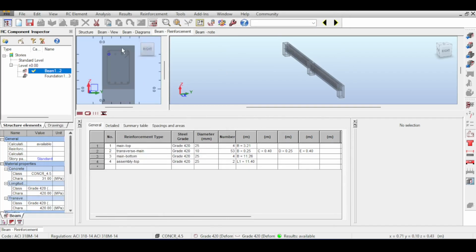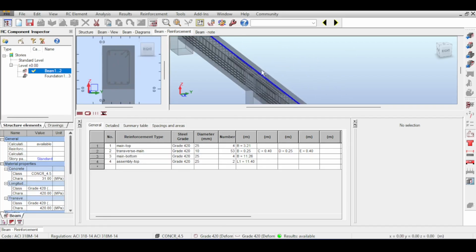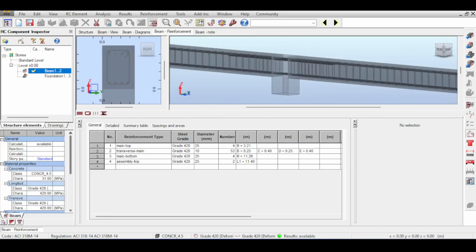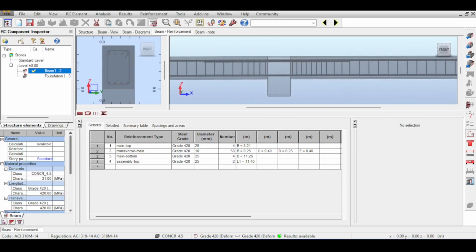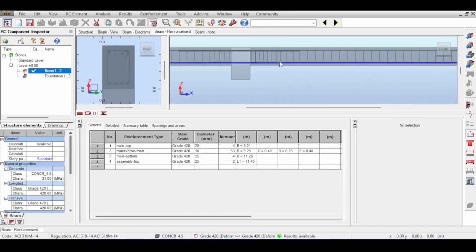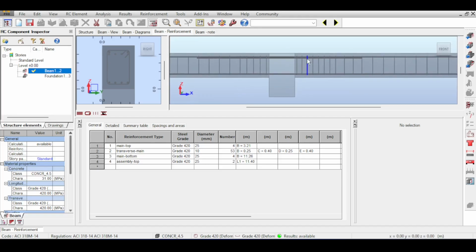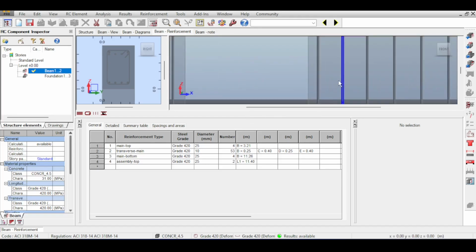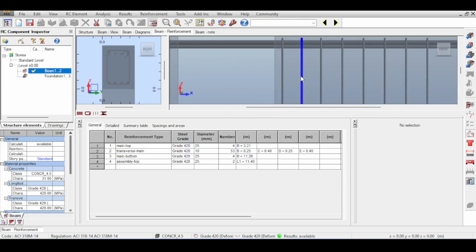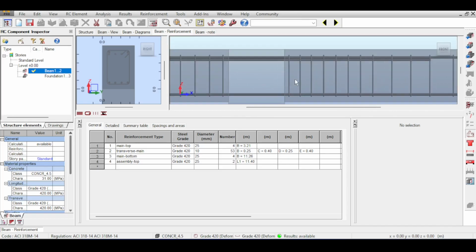All right, so you can play around, and I think I have reached a beam that I kind of like, but there is one problem left. The problem that I have now is with stirrups. Look, here you have a spacing, here you have a different spacing, here you have a different spacing. This is nice and dandy, but it seems that my stirrup spacing is not even to the closest 5 centimeters, which causes practical problems.